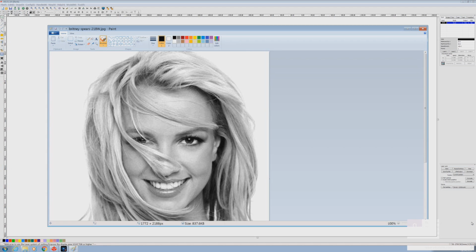The power of the laser gets changed incredibly quickly as it scans across a single line. It's a continuously varying power. You may have noticed on your machine and in the software that there is a facility to specify a minimum power as well as a maximum power. Well, what we can do, we can actually soften this picture or make it harder by changing the levels of power that we put into our program.